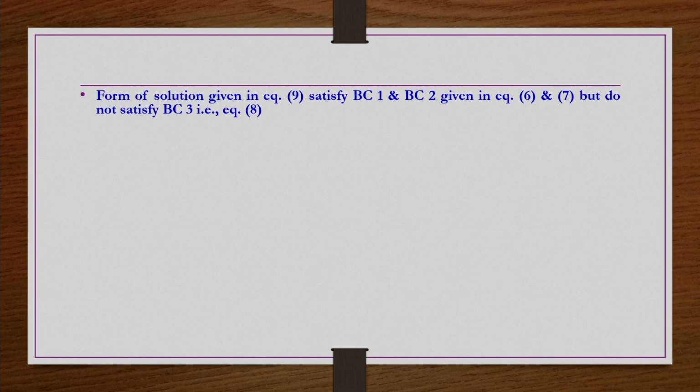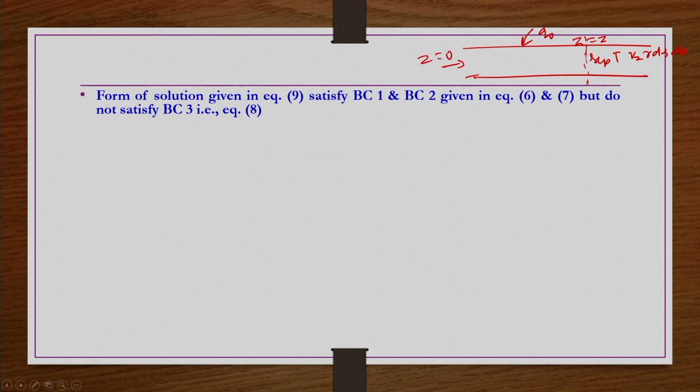How do we try to do it? Let us say this is the pipe, and consider a certain location z, from the inlet z equals 0 to z equals z. Heat is coming in because of the constant heat flux, that is 2 pi r z q naught. That should be balanced by the rho Cp T Vz r dr d theta, on integration, whatever the quantity is, at z equals z.